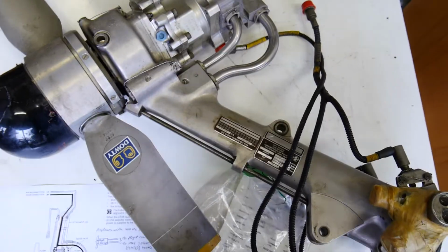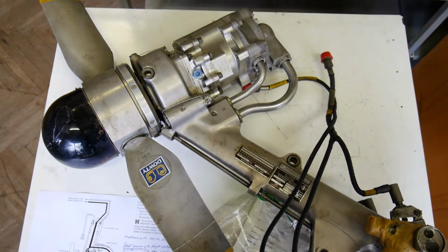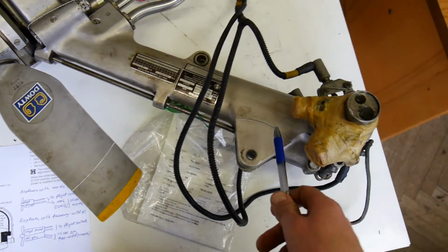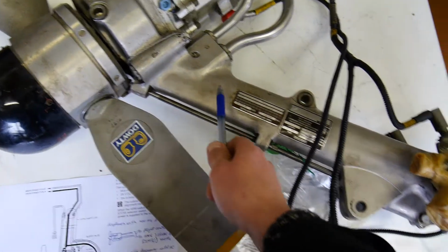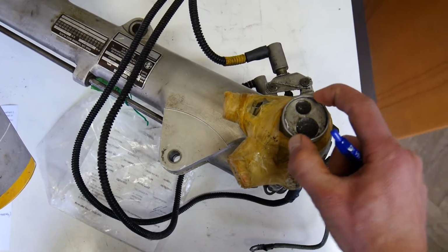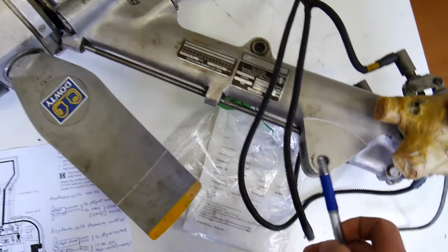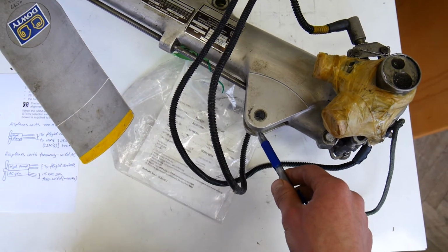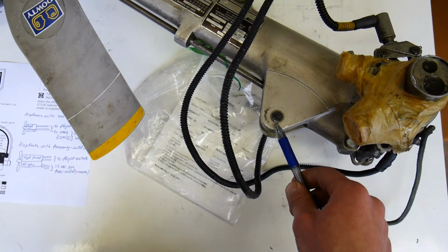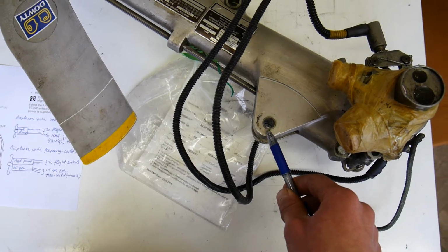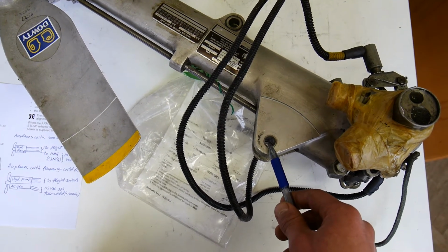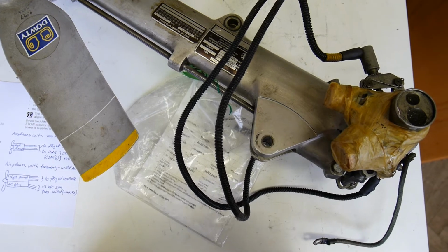Generally speaking, the RAT consists of several parts. The leg is attached to the airplane from this side. Further, the actuator, which is removed. The actuator is connected here. This is the deployment actuator, which helps us to ultimately release the RAT, as well as to stow it back into the airplane.